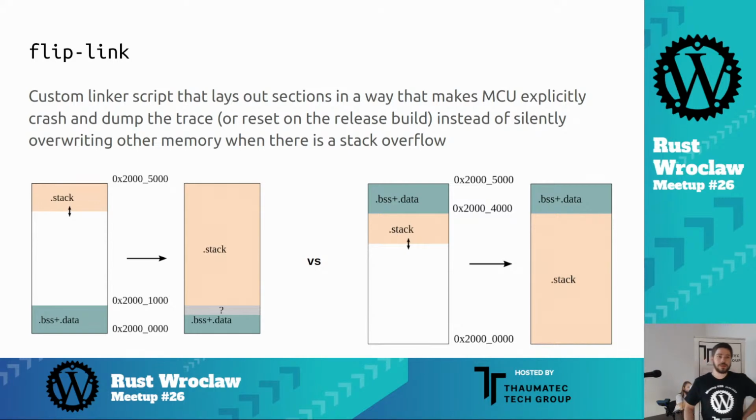So the problem is that the standard layout of memory in the ARM Cortex-M is that you have BSS plus data. This means all your variables that are static, because you don't have heap. Usually you don't use heap on the microcontrollers, or at least you don't use the global allocator. So most memory you will need throughout the entire time of the program, you will just statically allocate. So it will land here, and the problem is that you have this stack